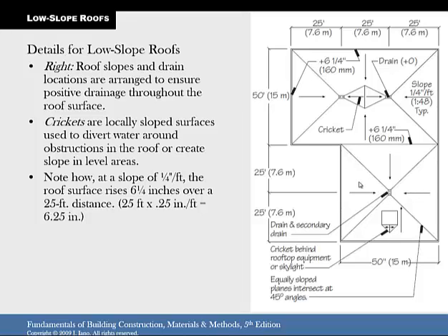You say 16 inches divided by 35 feet is going to give you 0.46 inches per foot. But it's asking you to say the nearest 1/8 inch. So 0.46 would round up to a 1/2 inch per foot, but that would exceed 16 inches, so you got to go down one, so the next 1/8 inch would be 3/8 inch per foot. Does that make sense? So the maximum slope would be 3/8 inch per foot, not to exceed 16 inches on the edges.